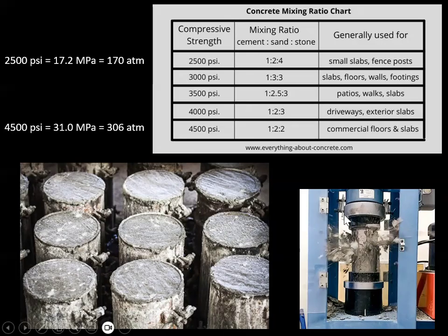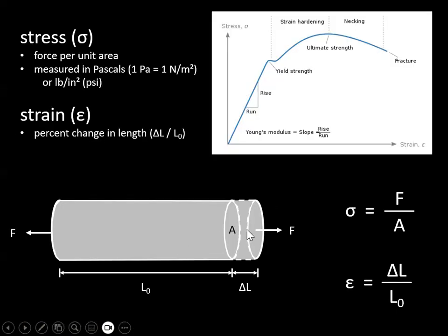But suppose it's steel. Oh, now I could stretch it if I want. Now it's steel, so you get this whole tail on this curve here. You guys see it goes up to this ultimate strength? But once you pass the yield strength, you're beyond the elastic zone.